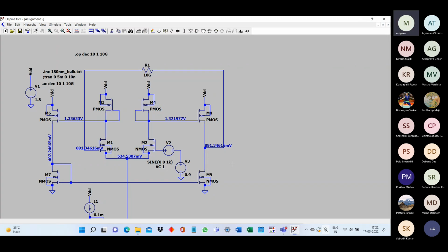For the time being, just understand that we will do the detailed analysis after going through the feedback theory. For now, you can understand that this high pass filtering effect is coming because of the parasitic capacitance and R1 forming a high pass response. We will look at that once we understand the loop opening and how to analyze the feedback.